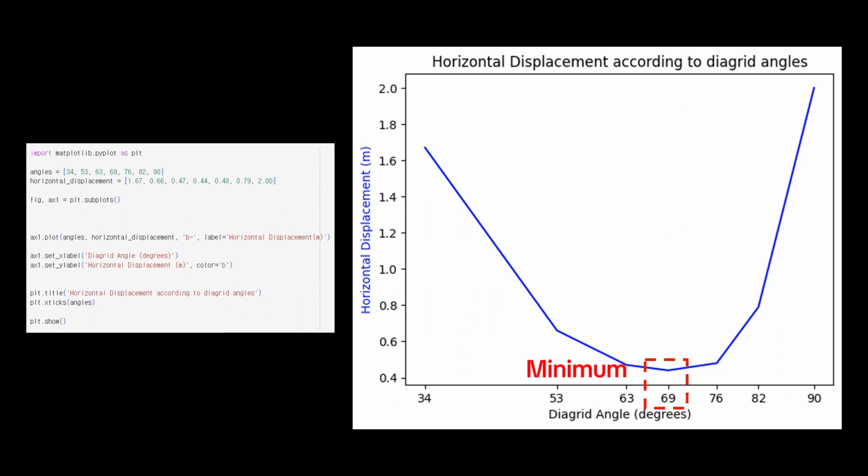That is, it was found that the lateral stiffness was not very sensitive to the angle in the 69-degree region. Through this, for an aspect ratio of 6.67 and a building with 60 floors, the zeta value is optimal at bigger than 65 and smaller than 75.